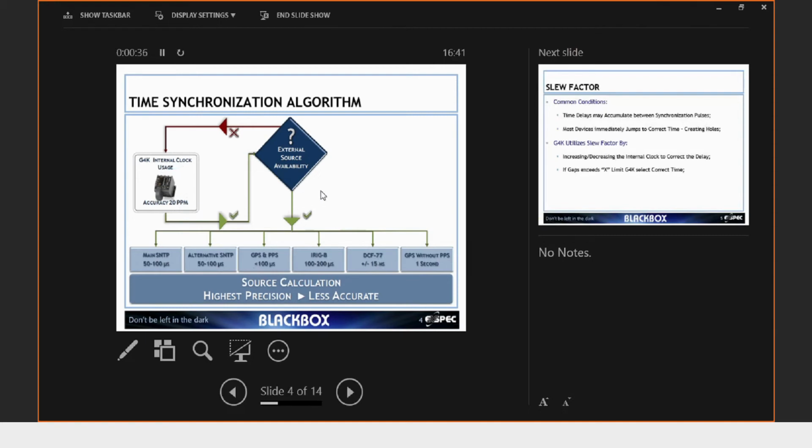That's the internal processor offset. Even if you take 24 hours, over 24 hours it might be maximum. Of course, it's not always 20 ppm. Let's say if we produce 5 units in our production site, some of them will offer 10 ppm, some 15, but we guarantee not more than 20 ppm. So the worst unit, which will be 20 ppm, will offer approximately 1.5 seconds time offset over 24 hours.